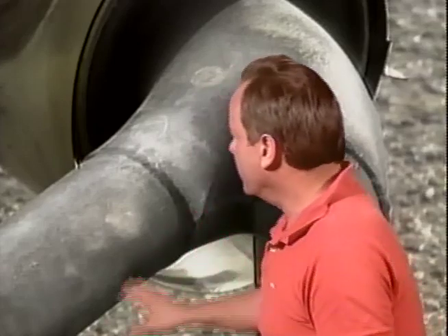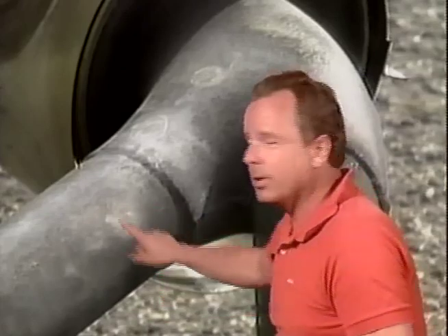Can you repair exhaust system components in the field? Well, it's not recommended, according to the FAA, that you repair exhaust system components in the field. Also, how do you clean ceramic-coated exhaust components? Well, if you do have ceramic-coated exhaust components, they should be cleaned by degreasing. And once again, lead pencil marks shouldn't be used because they can cause corrosion right there.